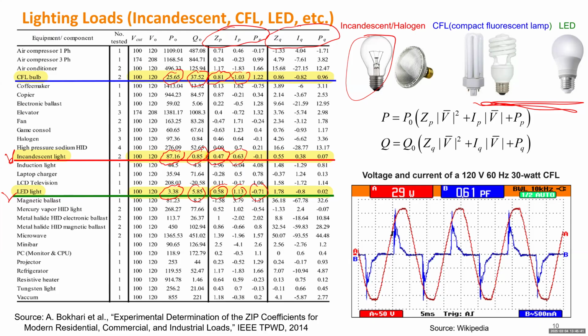The current is generated by this specific device. If the current has a very similar sinusoidal waveform, in exactly the same phase, that's power factor 1. If the current waveform is lagging the voltage by any angle, that's not power factor 1. Also, even if they have the same phase, reaching the peak value at the same time, if the waveforms look very different, that's also reactive power.